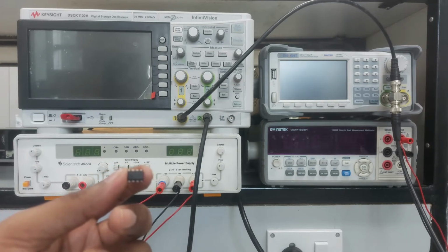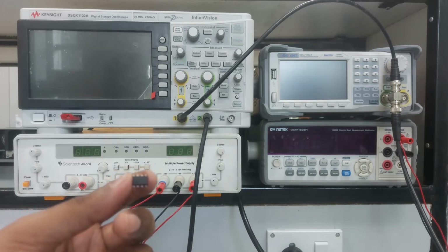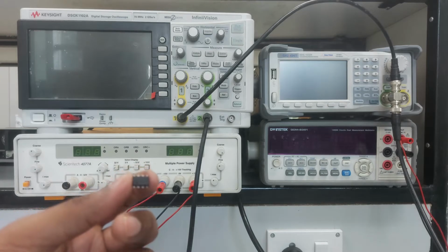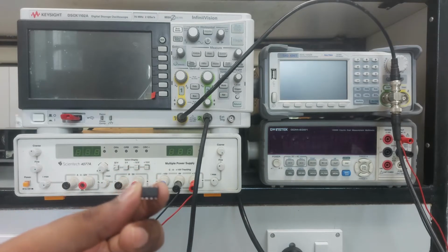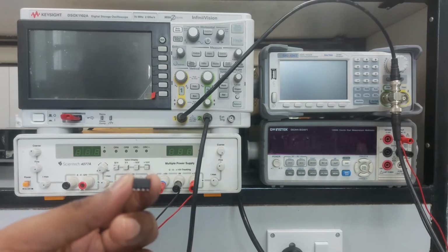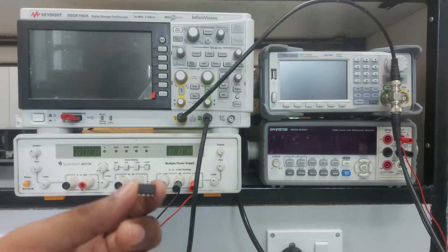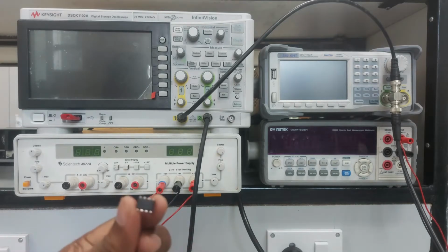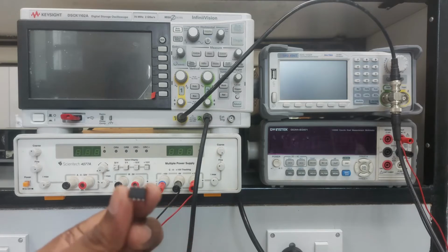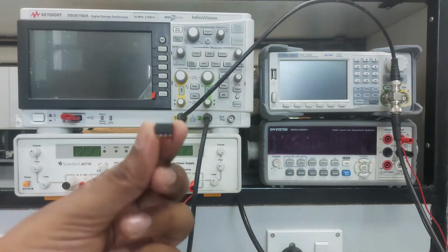Now gain will come to 10 to the power 6 to 10 to the power 5. If we increase the frequency from 100 hertz to 1 kilohertz, gain will come down 1 order per decade, so gain will come out 10 to the power 4, and so on. As we reach the frequency 1 megahertz, gain will become around unity. So it has finite bandwidth. We can operate this op-amp with a frequency of input signal within the bandwidth, so that we can get the constant gain.